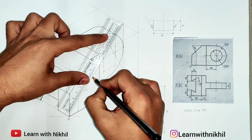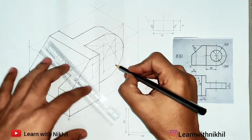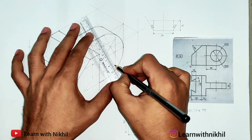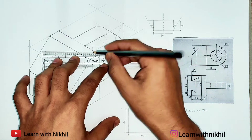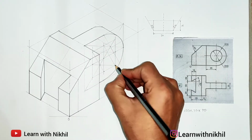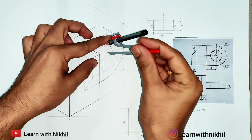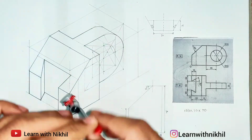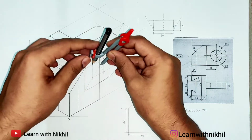Now finally, again the diagonal line is already present. From the opposite ends, joining at the midpoints of the opposite sides. As there are many lines, just make the center points dark. So this is the point, this is the point, and finally this is the point. So from these 4 points we will draw the circle. You know the process.